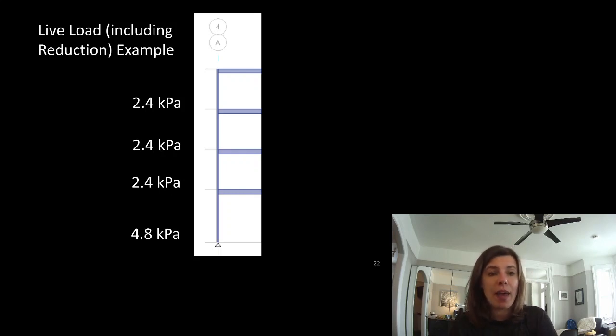So 4.8 kPa. Back in the day when you were allowed to go places in Toronto, if you ever went to the Fifth, it was a rooftop restaurant in downtown Toronto. Or maybe you went to Crocodile Rock back before they tore it down. Those had rooftop patios, 4.8 kPa, even though they were a roof, because they were accessible.